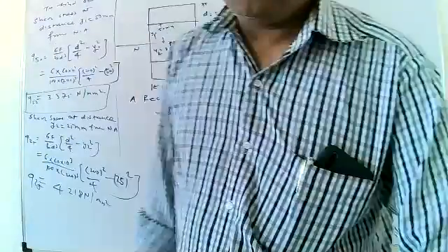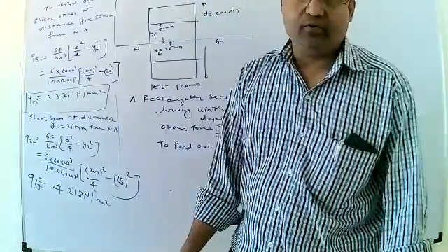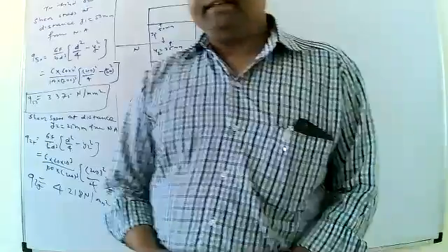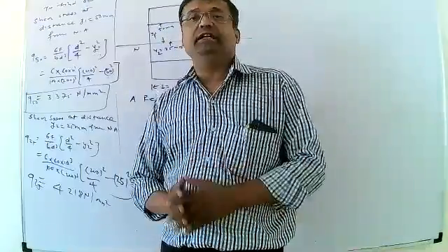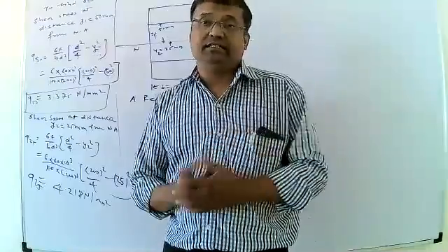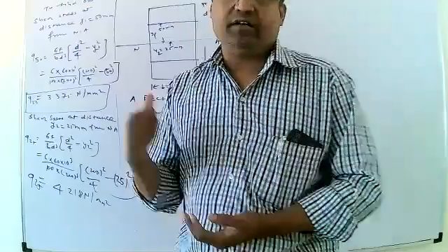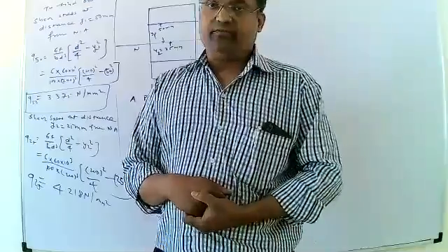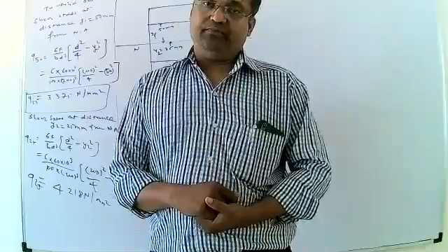This is a very simple way to calculate the value of Q25. In this problem, we need to calculate how much shear stress is induced at a particular distance. Here that distance is given as 50 mm above the neutral layer and 25 mm below the neutral layer.